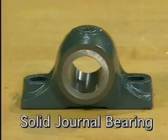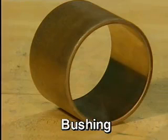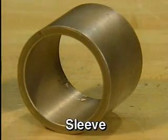Solid journal bearings consist of a solid one-piece sleeve mounted in a one-piece housing. A solid journal bearing is sometimes called a bushing or a sleeve bearing, depending on its thickness. A bushing is a relatively thin, solid journal bearing that gets most of its strength from the housing in which it is mounted. The term sleeve bearing generally refers to a thick-walled journal bearing.